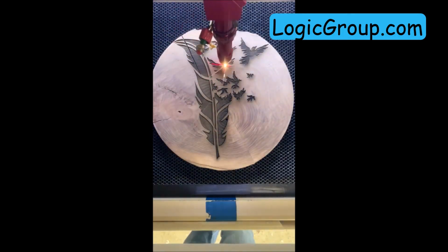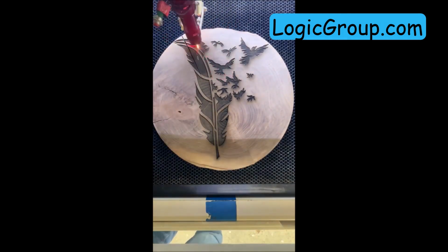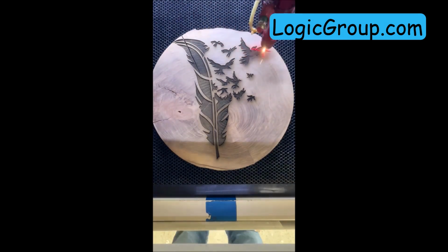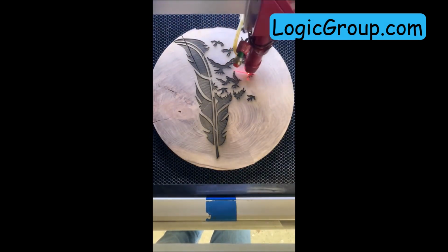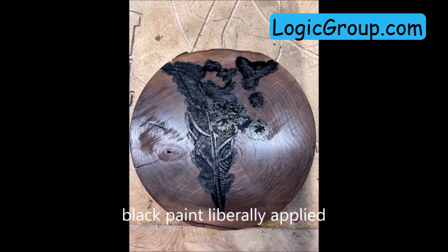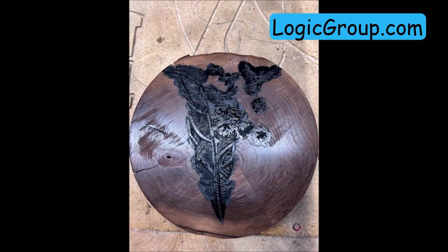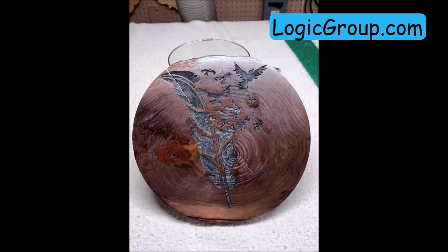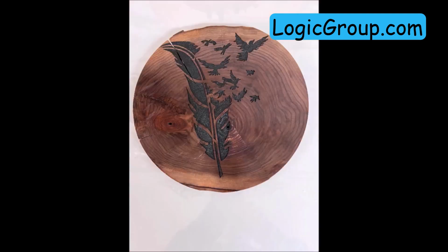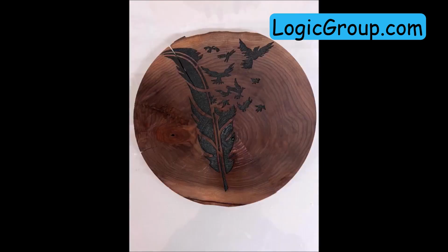Once I'm finished engraving, I'll remove the piece from the laser, and then I'm going to give it a spray coat of clear lacquer. I want to seal it, and then I'll paint those black parts where it's been engraved with a black paint. You need to seal the wood before you paint, or the paint will run through the wood. After the paint application, then you sand the whole live edge piece right down to the black walnut, and give it 3 coats of finished lacquer.